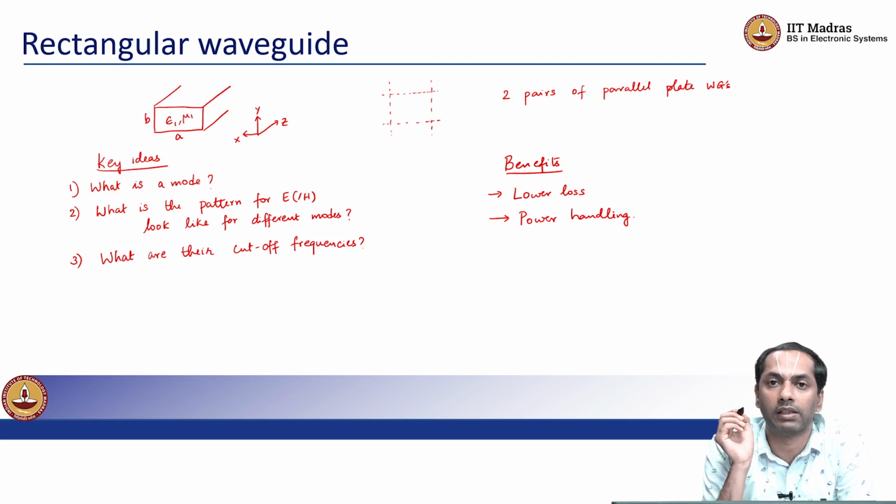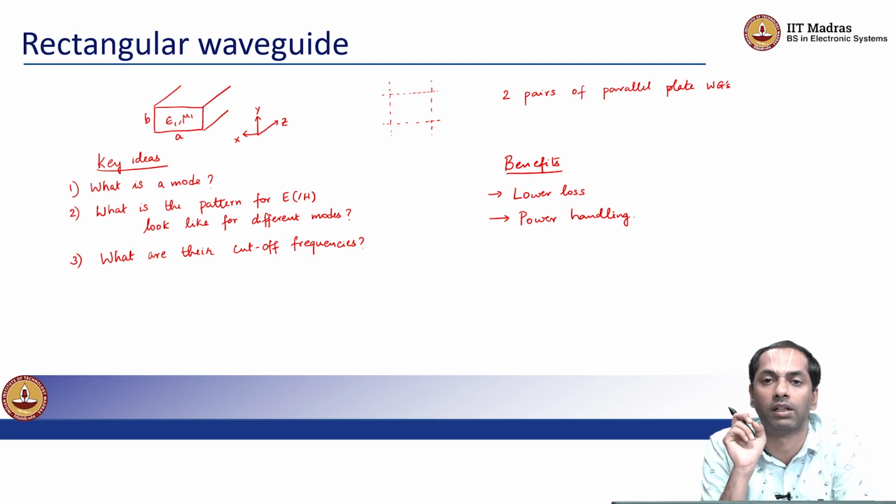So again, taking the example of the coaxial line, you remember that the fields are highly concentrated around the central conductor, right, whereas the ground conductor has a much larger circumference, right. So the fields have a lot more surface area to terminate themselves, whereas near the central conductor the electric field concentration, or the intensity of the electric field, gets very large.